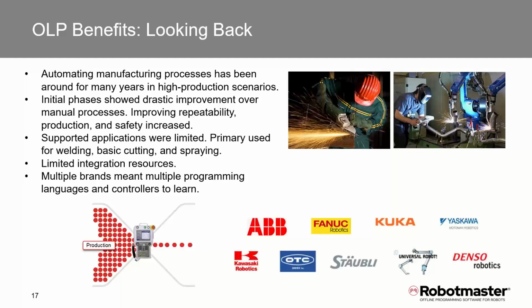And with that, limited integration resources were available. Integrators started to notice that they may not be able to take a one brand solution. For example, they would implement an ABB robot at one facility, and then notice that for the next application they may have to go to a Fanuc or a KUKA or a MotoMan for a better fit. So that introduced another challenge. The first challenge was that programming was taking way too long. The second challenge was that robots were already hard to program and required quite a bit of robotic experience. Throwing multiple programming languages and multiple controllers on top of that added another degree of complexity.